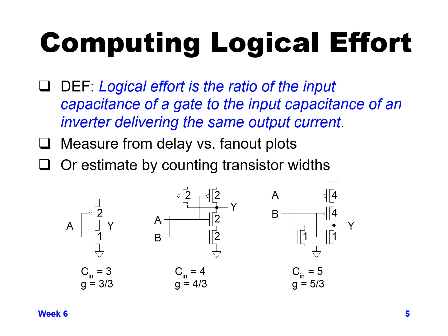We take the Cin for either input is going to a PMOS of size 4, NMOS of size 1. Add the 4 and 1 together, we get a Cin of 5. Normalize that by dividing by the size 3 inverter normalization, and our logical effort for a 2-input NOR gate is 5/3, so 5/3.